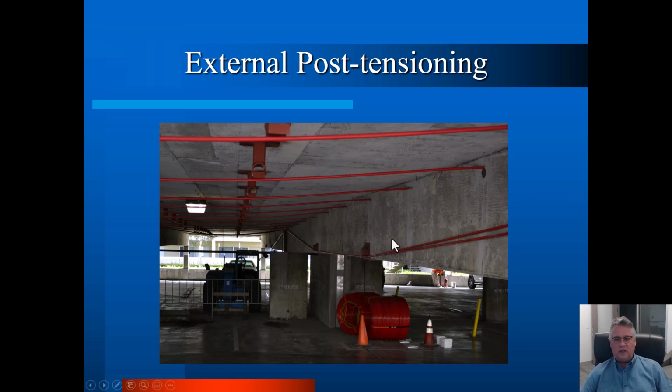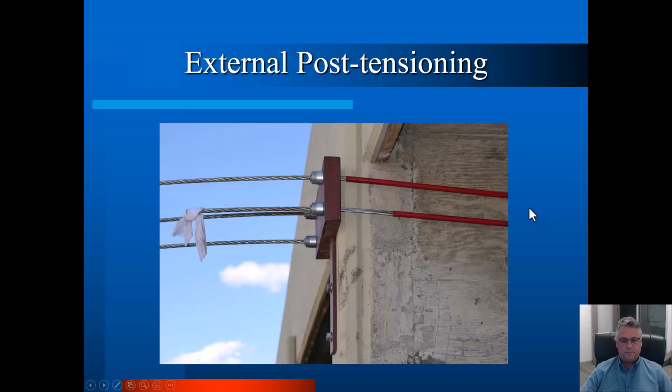So this is that same project. This is actually the sister garage. A few years after we did the previous garage, this one started having worse problems, and we ended up putting a deck over the top of this because they had really let it go. So we had to strengthen the beams to support that new weight. We strengthened the slabs so that they wouldn't fall down, and we designed the new post-tension slab to span beam to beam up above. So this was a fun job.